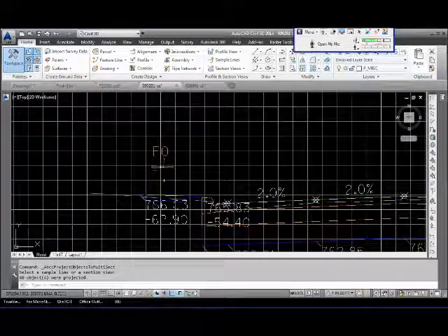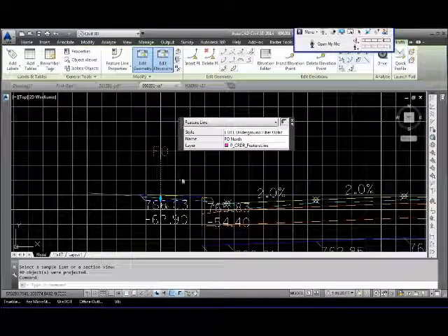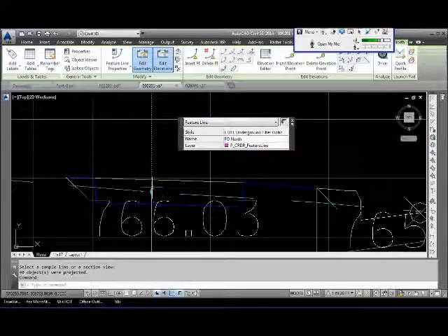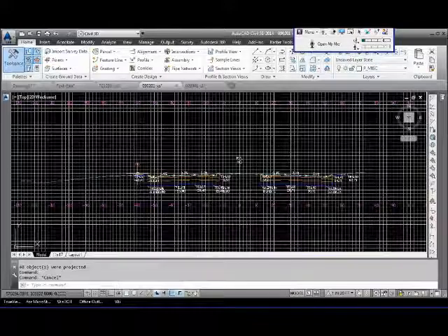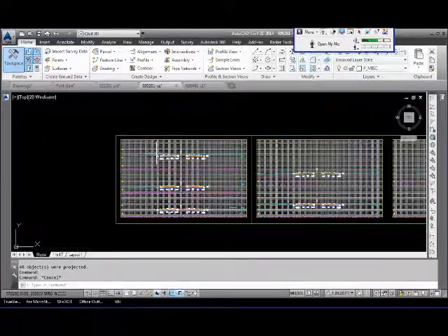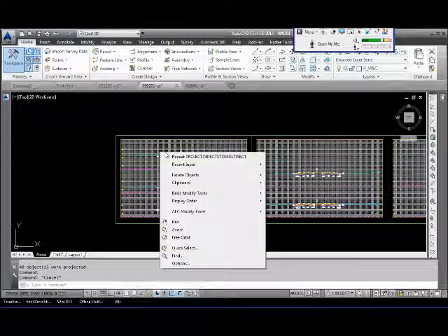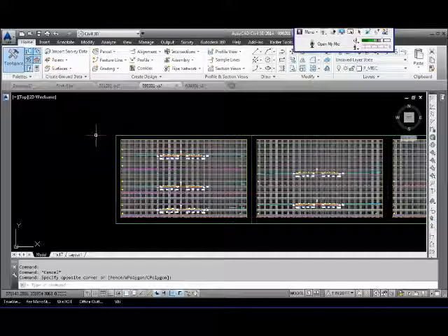We can see my fiber optic is here, where that alignment or that feature line is, and it's snapped on my existing surface. So it gives you a quick, nice, easy way, and you can do basically an unlimited amount, not unlimited, but within reason, that amount of feature lines can be projected on your section views. If you have feature lines, you can always pop them onto the views.